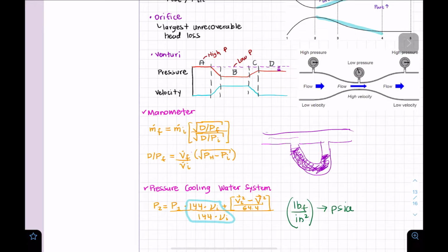So we have the fluid moving in this direction or moving in that direction. We will see the pins, right? And I will go over that one later. In this case, it's going that direction. So this manometer is a U-shaped tube of glass, and it's going to be filled with some liquid, right? And we're going to try to measure the differential pressure.